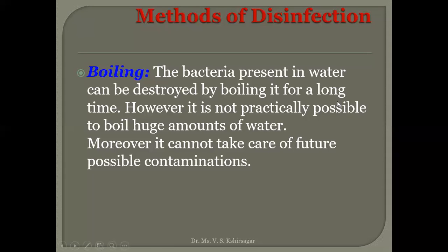The bacteria present in water can be destroyed by boiling it for a longer time. We are not supposed to just boil, close the gas and turn off the flame, and think that 100% of bacteria are killed. After the boiling point is reached, you need to keep boiling for a few more minutes, a minimum of 5 minutes, and only then will the bacteria get killed. However, it is not practically possible to boil a huge amount of water. Moreover, it cannot take care of future possible contamination.